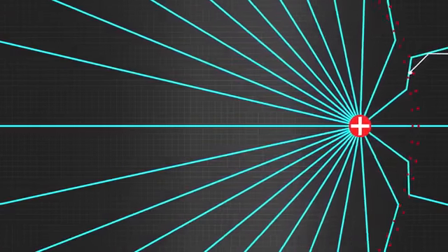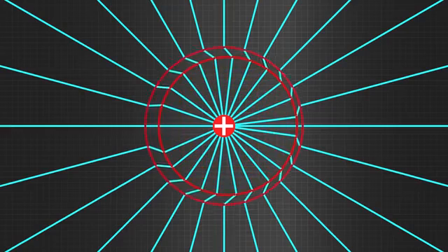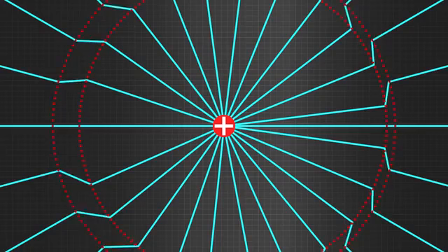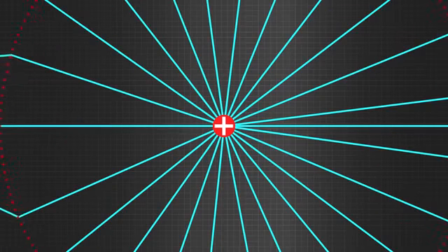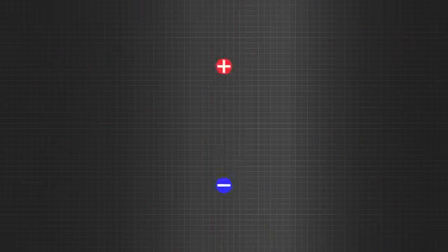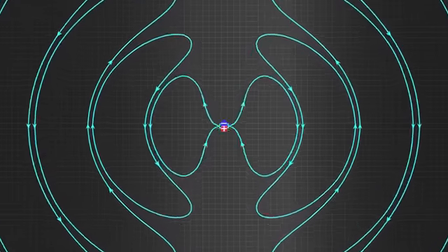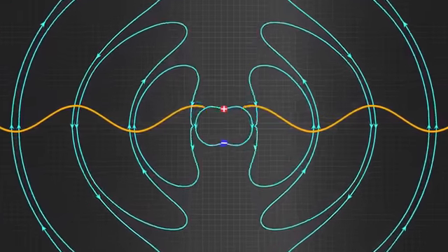To show the kink animation in a clear way, let's move the camera along with the charge. We can say here that the acceleration of the charge has caused an electromagnetic disturbance, or electromagnetic radiation. Based on this understanding, we will be able to understand the most important experiment in the field of antenna technology, the oscillating electric dipole. The interesting fact about this simple oscillating dipole is that it produces electromagnetic radiation in a perfectly sinusoidal manner. Let's see how it is achieved.